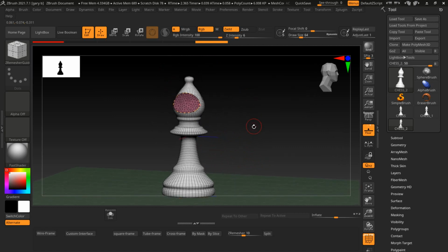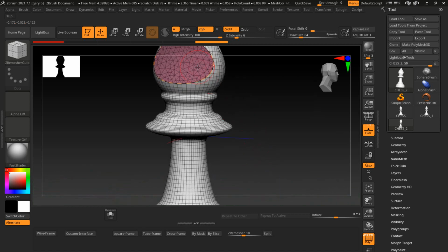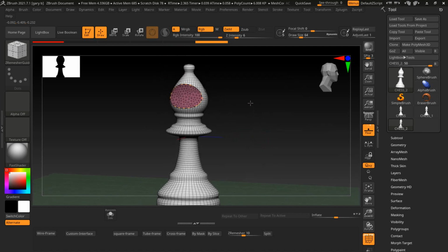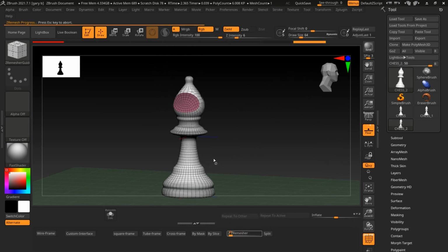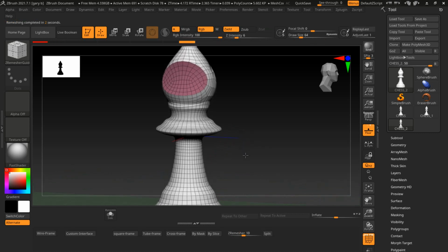Now, if I want to lower the polygons on this here, I'm ready to go, because when I do my wireframe, I got triangles right here where it's polygrouped, it's going to be triangulated also, so I don't want that to happen. So basically I'll just set this to, let's say, 2 and press enter. Alright, then that made it just like I wanted to.